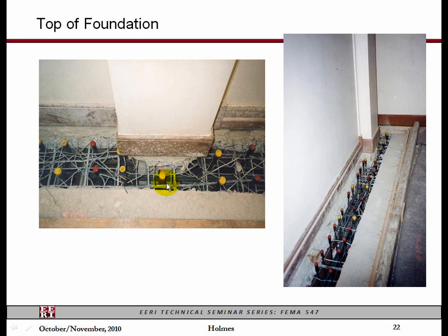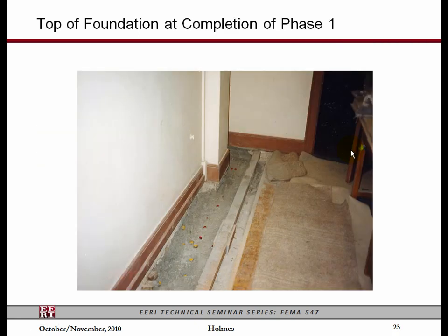a coupling. So these are all couplers. Here is the existing reinforcing in the slab. The other thing, when you cut through a slab, you have to be careful. You're going to lose its vertical support in some cases. This particular one was shored to get this continuous slot, and then the reinforcing was put in with couplers so that the next summer the shear wall could continue its construction.